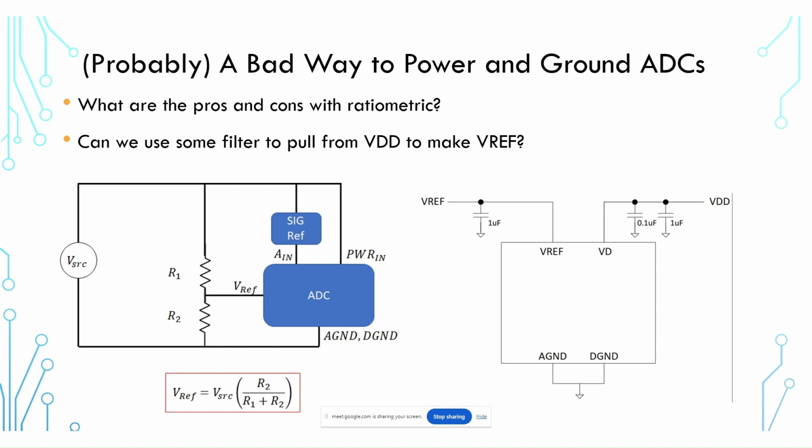It's related to the topic generally of power integrity in digital processors that have multiple voltage inputs, sometimes operating at the same voltage level. A common case on large processors is where you have your standard digital I/O supply, but then at the same voltage you have another supply, such as for PLLs, which are used to generate clocks internally in the processor. In that case, sometimes people will try to use the exact same strategy that I mentioned here in this bullet point, which is to basically apply a filter between the standard digital input and that auxiliary input that needs to operate at the same voltage.